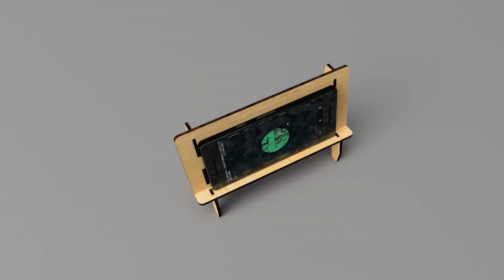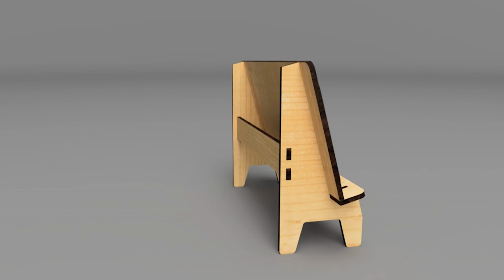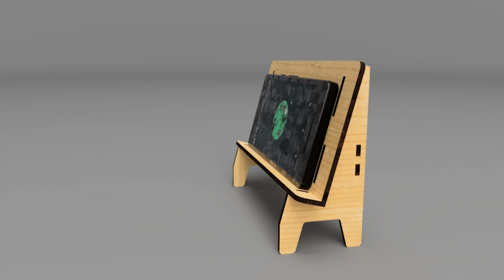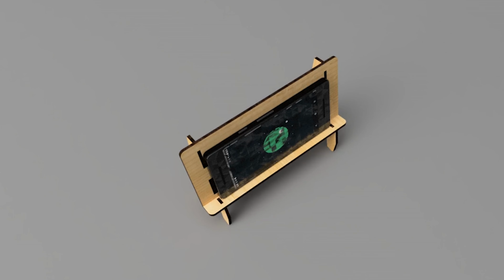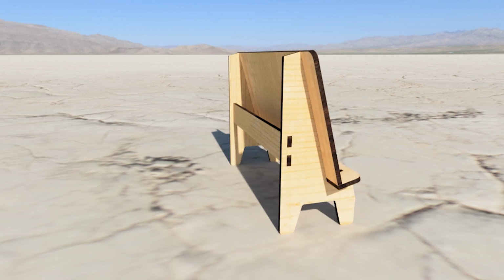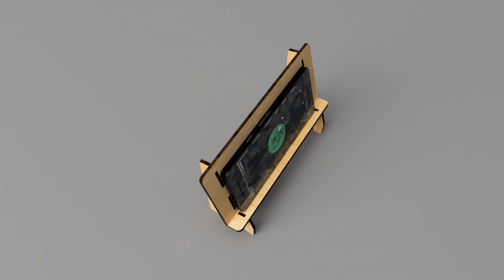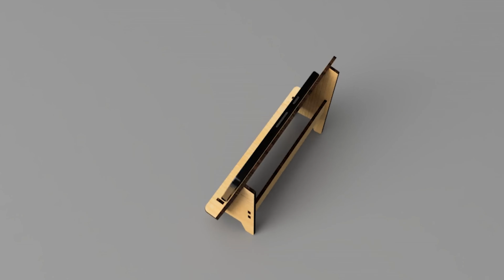In Fusion, we can use the power of parametric modeling to create objects like this laser cut cell phone stand very quickly. We can model it in 3D, then we can lay the parts flat and create a tool path. We can even set up a tool that has an editable kerf so we can account for kerf when we're cutting out our designs to ensure a tight fit.